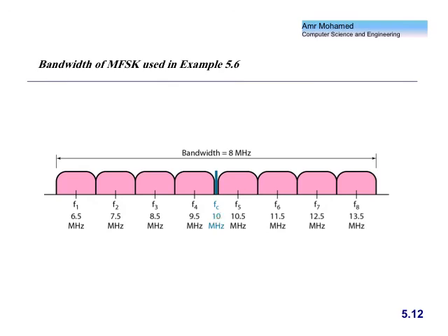So I have to split the whole signal into 2 halves around this carrier frequency. Since I have 8 and 8 is even, I put 4 of them on one side and 4 on the other. So this is the carrier frequency, 10 megahertz. Minus 1 megahertz gives me this signal and this signal and so on.